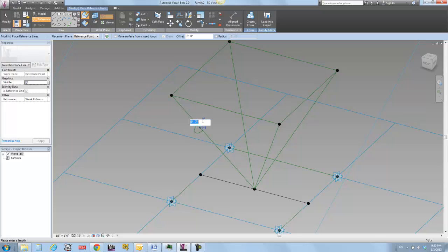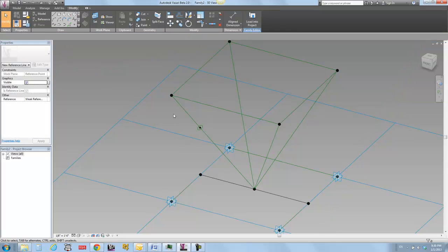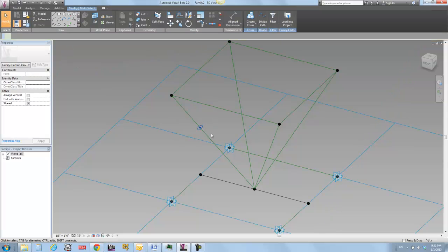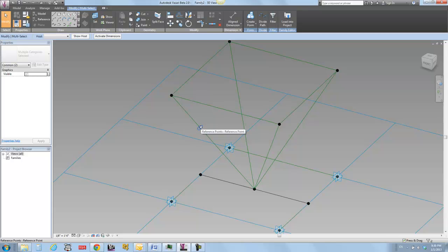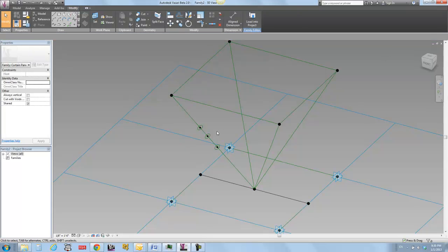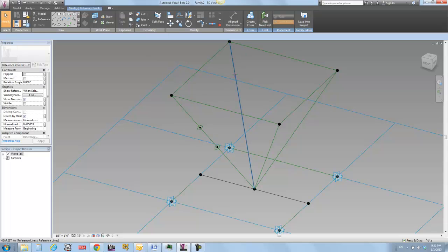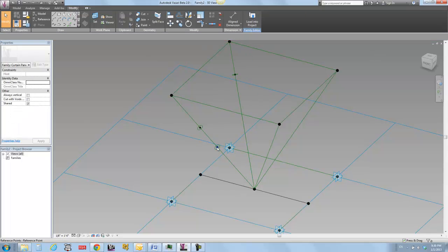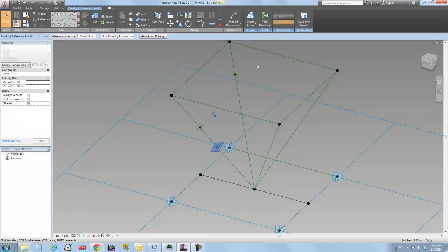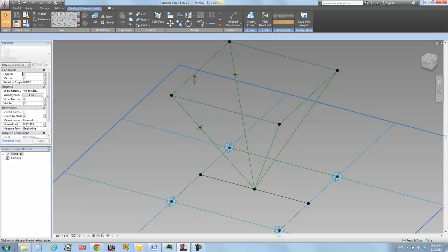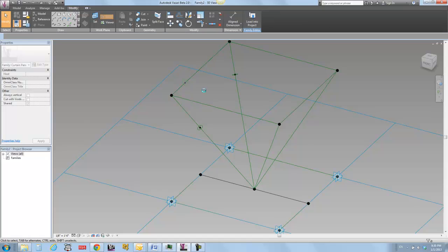And let's say that that's going to be maybe 3 inches. And I'm actually going to use that because I'm going to want to do a couple copies of this. So I'm holding down the control key here and I'm dragging and I'm dragging. So now I have 3 of those guys. I'm going to select the point. I'm going to pick a new host, put it over here, and just because I know I'm going to need to put a couple other profiles around, I'm going to pick a new host, and this just makes it easier. And so these guys are both 3 inches.